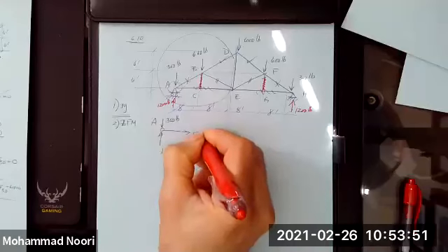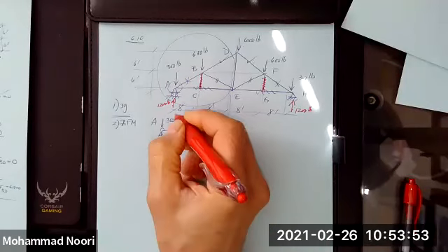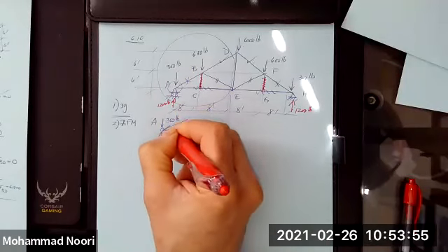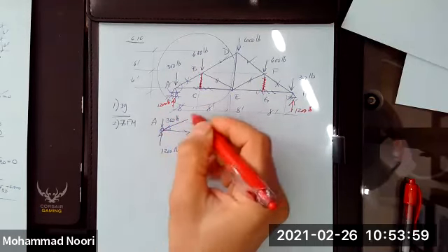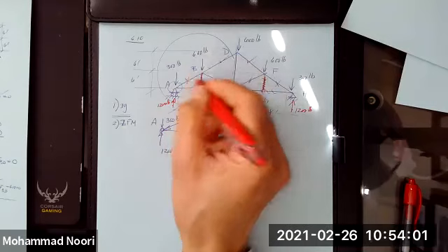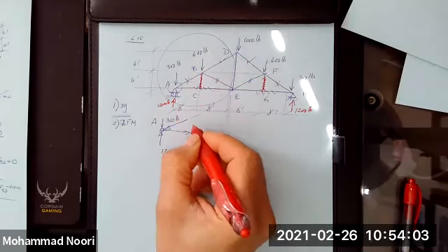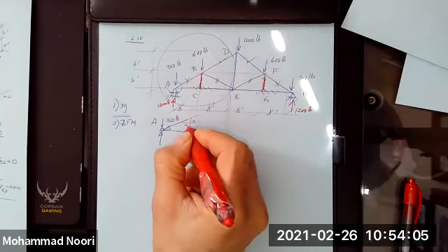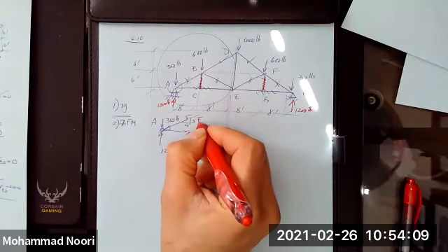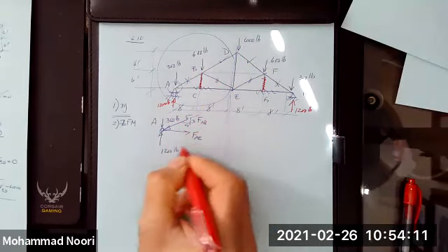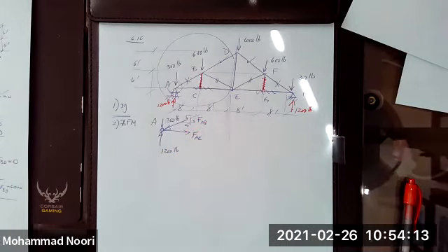Recognize or detect the symmetry. Okay. So I will start with the free body diagram of the joint. If you look at the geometry, you see this is going to be 3, 4, 5. So this is the force of AB, assume that direction, and the force of AE.